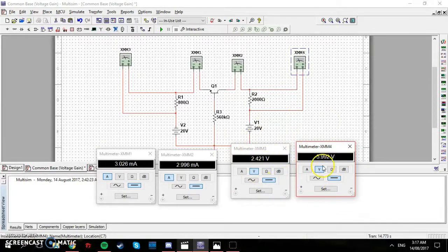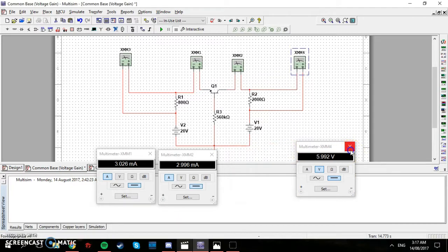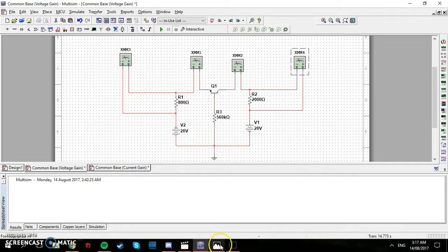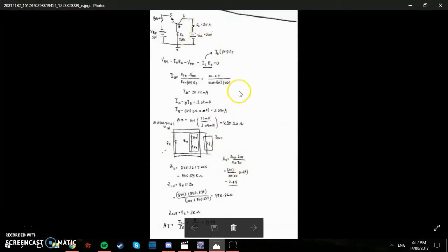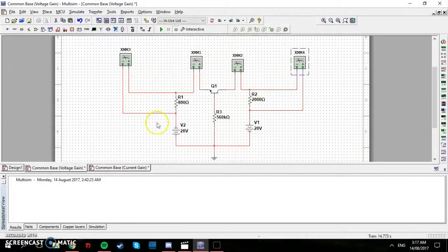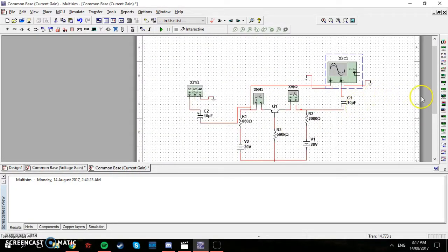is a voltage gain. Calculating it, you will get a voltage gain of around 2.5. Now to check these values, you have to manually solve the circuit using approximation formulas. Shown here, using these formulas, you get the parameters of the circuit, and with AC analysis, you can get the current gain and then the voltage gain. Here's the voltage gain, which is 2.48, and a current gain of 0.99, which means that this circuit here is correct.